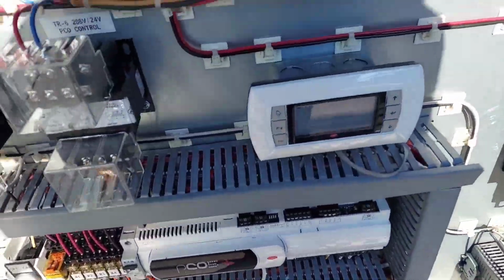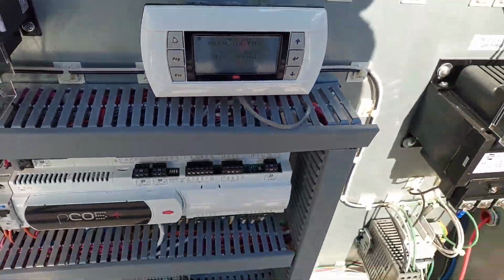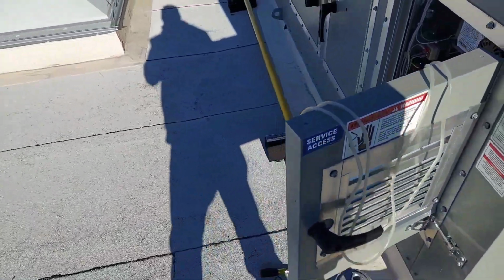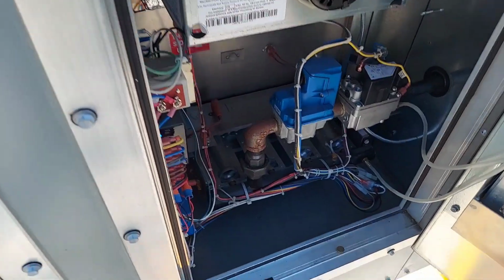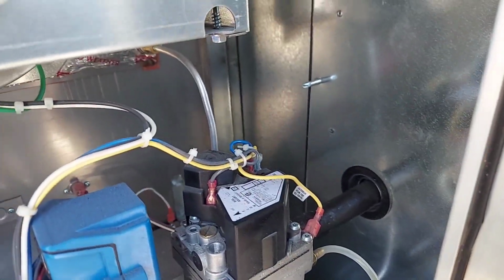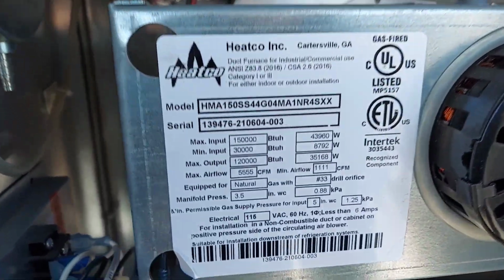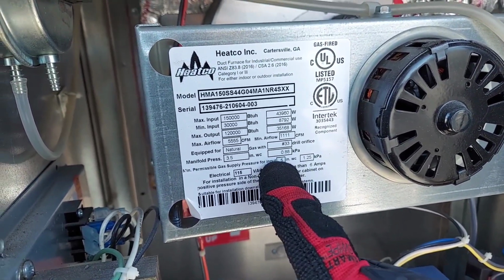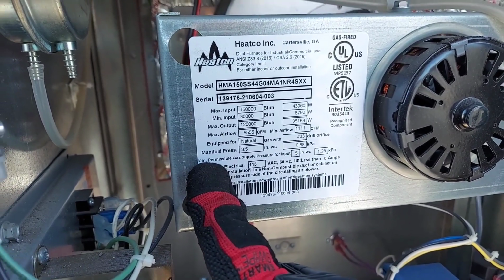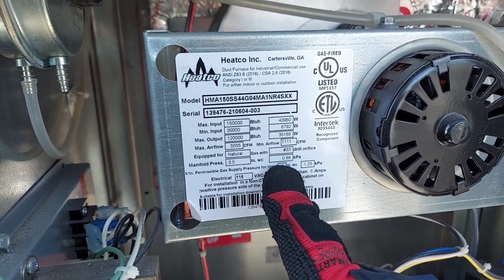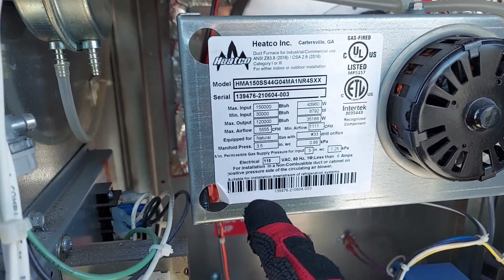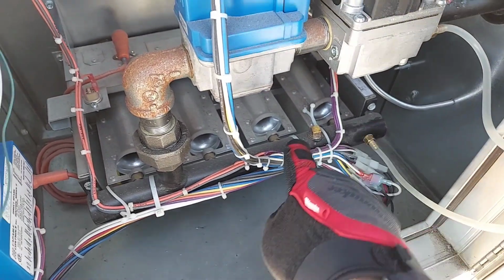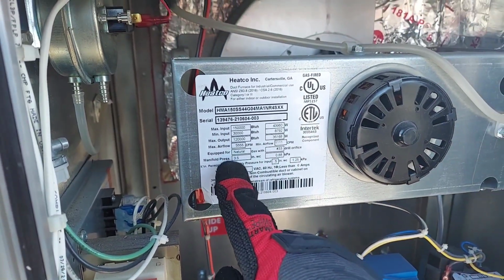All right, so usually with the gas furnace, the manufacturer will send the specs, or you can just look on the gas valve to see the ratings. For example, in this case, you can see that the input gas supply pressure, this is the minimum permissible, right? It's 5 inches of water column, and the manifold pressure, which is over here, is supposed to be 3.5.